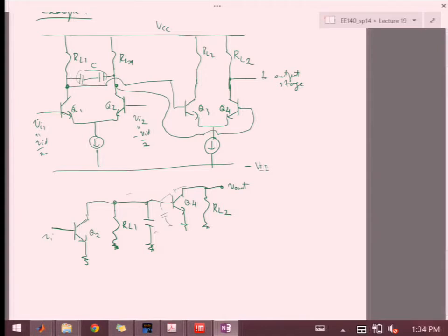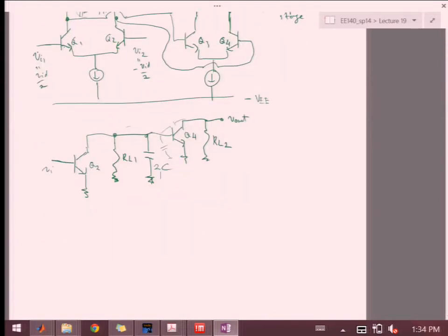Double. So this has to be 2C. Okay, so now we have our circuit. Let's say the C that I'm adding has to be reasonably larger than your transistor capacitances. Keep in mind that I have to shift the pole divided by A0F. A0 is pretty big sometimes, 100, 1,000. So this has to be reasonably bigger than all the other caps in the circuit.